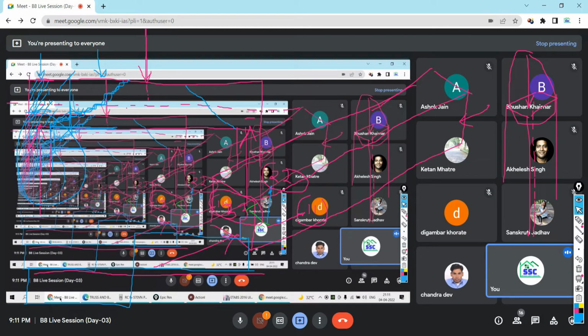Most of the time students are confused. What does it mean, axis 2-2? Or trainers just say that if you want to see the shear, just go to 2-2. If you want to see the axial force, just go to 1-1, and that's it. But what is the reason? I hope you all now know the reason why you are looking at 2-2.